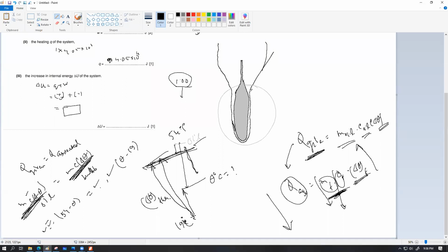To get the temperature here, we would have to heat up the entire amount of mercury. The idea is that the mercury, the glass, everything submerged must reach the same temperature as the external oil, which is 30 degrees Celsius. So that way the amount of heat that would have to be absorbed over here would be extremely high compared to a small hot junction metal for a thermocouple thermometer. This hot junction metal can take a small amount of heat to give the same temperature reading.